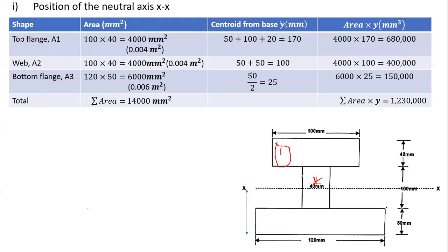But the width, the cross section on the other end for the same material has been given here as 40 millimeters. So we multiply 100 by 40 because this is 100, then 40 is across. Again, our answer is 4,000 square millimeters. If you convert to square meters, it's 0.004 meters squared, giving us the same value for the centroid is 50 plus 50. You have 100